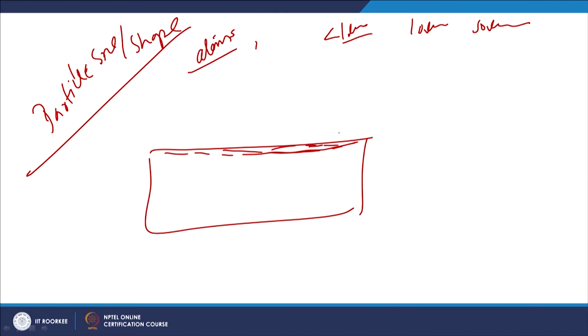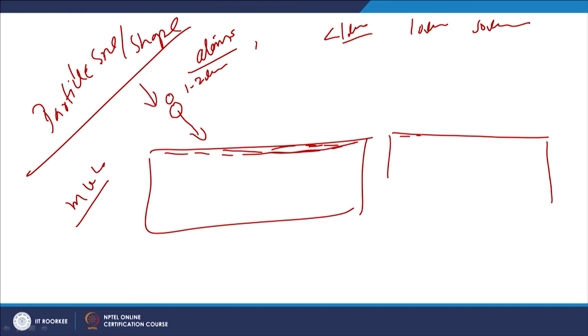So, removal of the material at the atomic level takes place when atoms are directed onto the surface. On the other hand, when very small particles, say 1 to 2 micrometers, are directed at a high velocity onto the surface, since the diameter is very small, they will have very limited mass. Despite having high velocity, if the mass is limited, it will not have much kinetic energy, and limited particles impinging on the surface with limited particle energy will lead to very little surface layer damage and deformation.